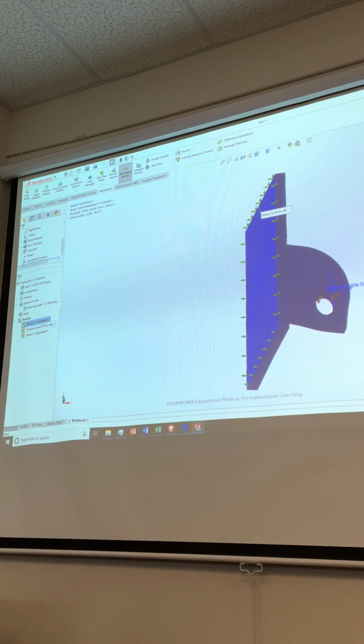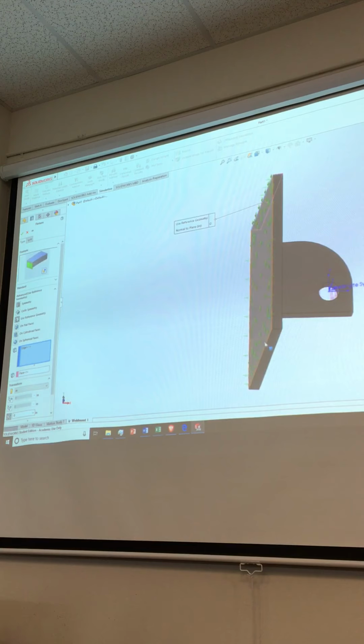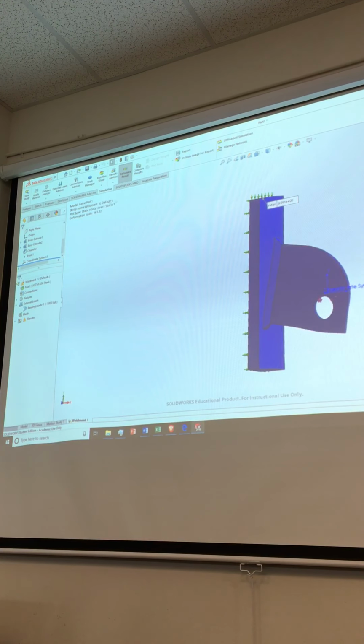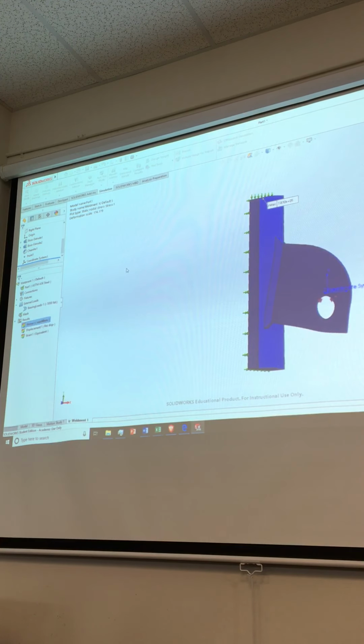Okay, well, let's go fix the boundary conditions. I think that was that one there. Edit the definition, right? I only had one edge on it. Let's click the bottom edge down here, same way, so that neither one of them can move and we'll share the load between them maybe. See if that doesn't help, as long as I'm far enough away from them. We could even try running this thing again here. Oh, I'm down to 700,000.